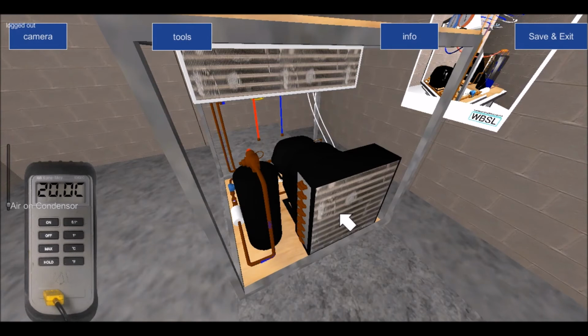So in our case, if I add 15 onto my 20, I get 35 degrees. So it's always midway. With an air temperature of 20 degrees, my condensing temperature can go as low as 30 and as high as 40. So as long as my condensing temperature remains between 30 and 40 degrees, and in our case it's 35 degrees, which is midway, which is spot on, we're quite happy with a 15 degrees delta T total. That's what we talk about.